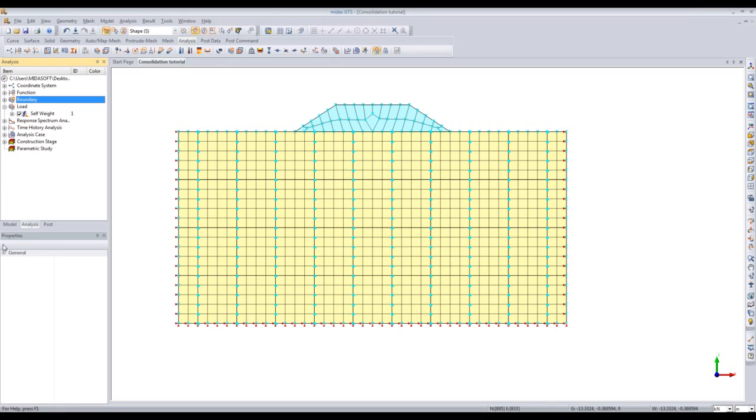Daryl, what do you mean when you put 10-meter head on the perimeter? What do you mean by this boundary condition? What is 10-meter head on the perimeter? Oh, okay. That's just the water level, so the nodal head will be 10 meters of water along this whole block of soil here. In other words, it's 10 meters of head that's uniform across the entire block. I guess the clearer way of putting it would be, that's your water level. It's 10 meters of head.